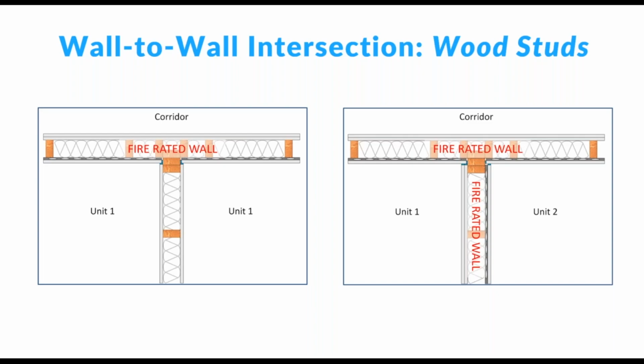So in wood frame construction, it can be fairly easy. We can use the design on the right, where it's a fire rated partition and unit demising wall between two different units, so we need fire and acoustics. At this intersection, in the middle here, we can stop the gypsum board so that it's not connected anywhere.